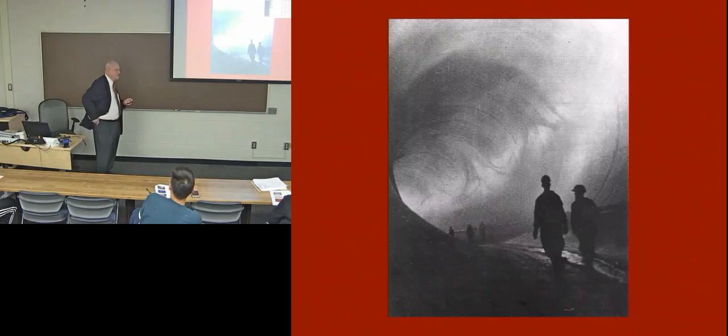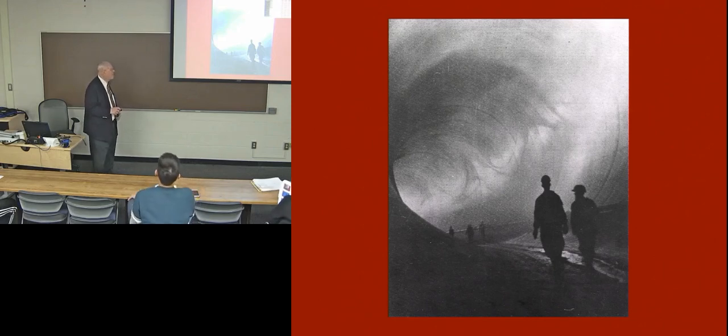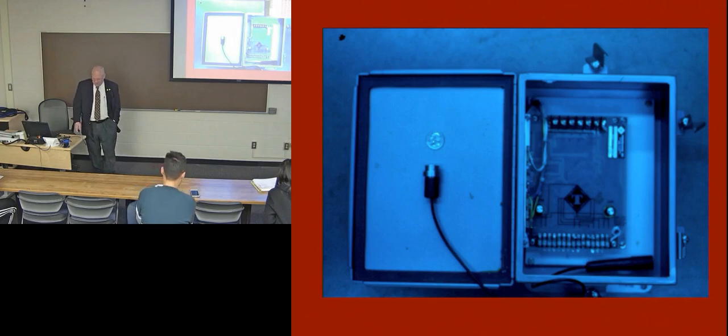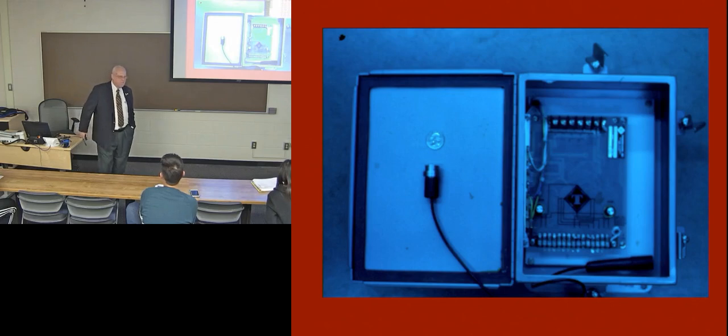This is what the inside of Tunnel 2 looked like. Tunnel 1 looked like that as well when they were all ready and finished. So, along the crown of the tunnel, we installed accelerometers. Here is an accelerometer and a control box. Many accelerometers coming into this box. Streeter predicted that when the water flowed through these tunnels, they would create an organ pipe effect.